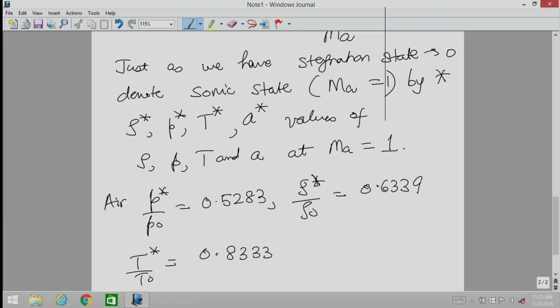That means the Mach number already would have gone more than 1. So even with half the drop of pressure for air, you find the speeds become equal to speed of sound and the flow becomes totally compressible.